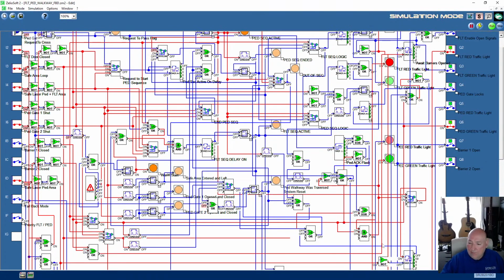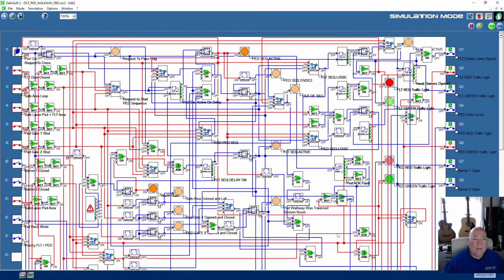It's counting down. Got 59 seconds to cross, so we'll cross the gate. Right, comes out of PED crossing, gives our 2 flashes, goes back into FLT. That all seems to be okay. We switch over to fallback mode. Right, so we're getting our flash on there, and we're getting our flash off there, which is the right way around. Yeah. That indicates we're in fallback mode.